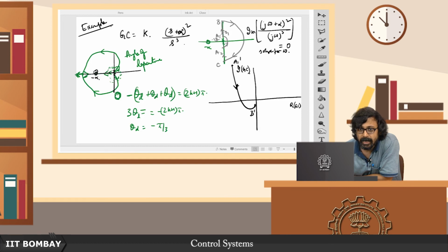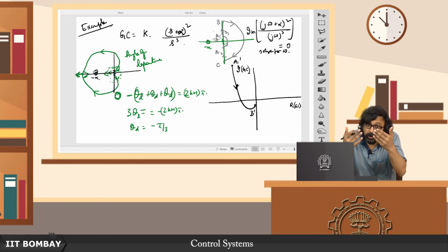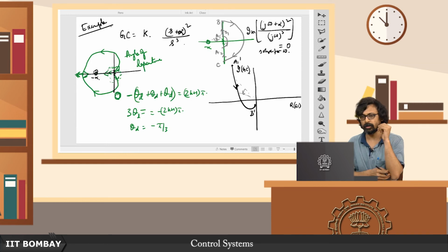As you go from A to B or A1 to B, as you keep moving up, the contribution of these zero pairs is doubled in the positive direction. That is tantamount to a counterclockwise rotation. So if you draw phasors from here and here, you see you are rotating in the counterclockwise direction, so the phase is going to monotonically come like this.